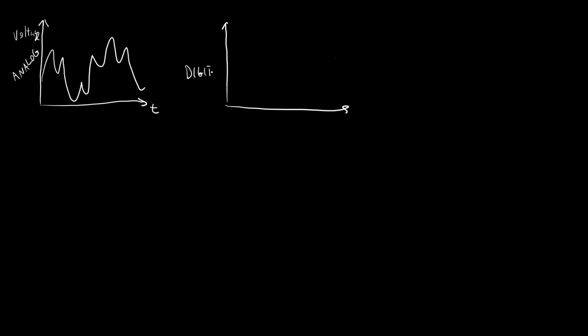Pretty much everything we have talked about so far in this video series has been analog, meaning if you make a graph of voltage versus time, you can have a continuously variable voltage that can take on any value between some minimum and maximum, whereas digital voltages are only ever going to be high or low. There's nothing in between. What exactly that high voltage is depends on the system, but common values, for example, are 5.0 volts or 3.3 volts. If you're working with an Arduino, different microcontrollers might have different high logic levels, and then low voltage is usually going to be 0 volts.